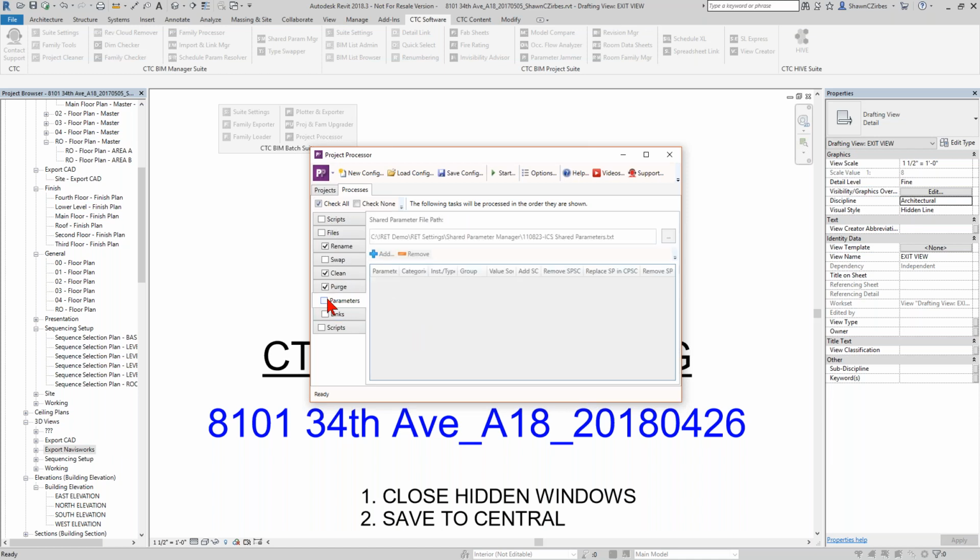You have the ability here to do some of the parameter adding and swapping in a schedule. So if you needed to do some major project parameter work, this tool can help you with that. I can process things around links where I want to find and replace paths. If I have absolute paths on things where I want to replace with absolute paths, I can do that in a hurry. I can force this to update a bunch of links in my model, Revit links and DWG links, to correct them to my standards.